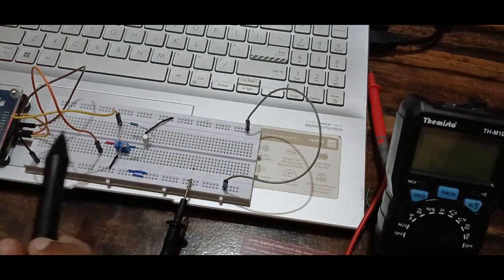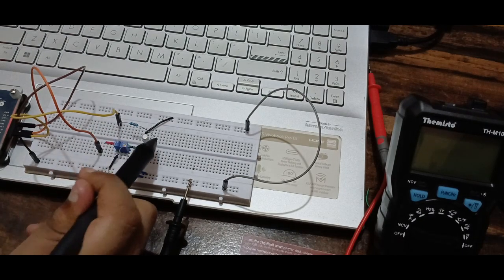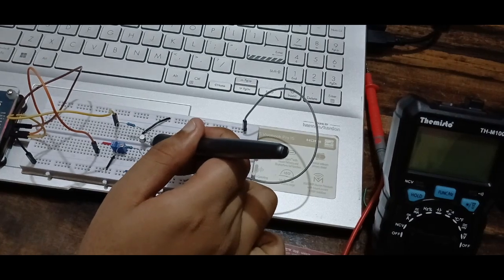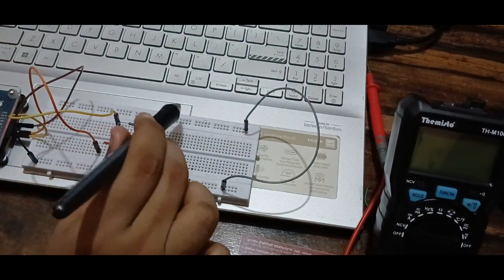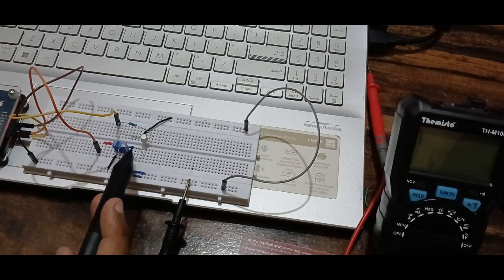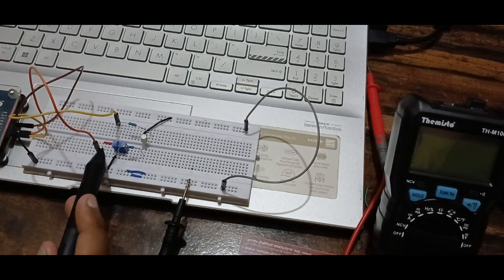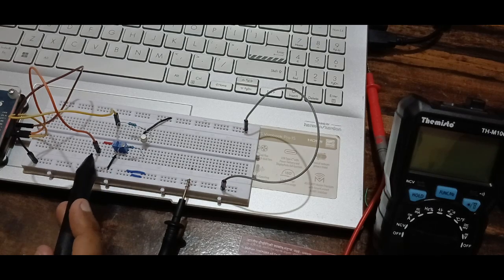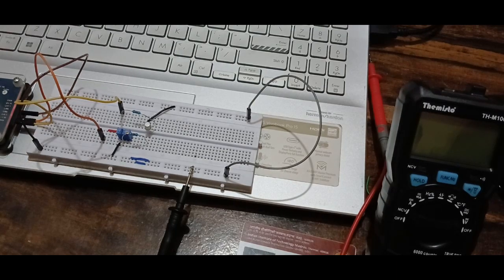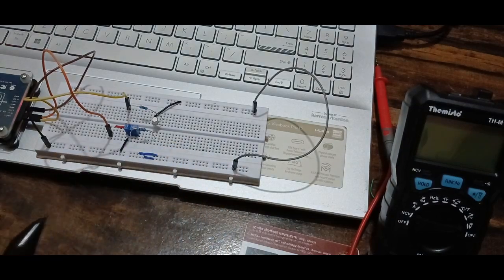I provide the VCC from channel A to the collector of this BJT, which is right there. This is our emitter, which is grounded. This is our base, to which I provided a resistor connected to the pot, and the third pin of this pot is grounded, and the first pin of this pot is connected to 2.5 volt. So now first I'll check the VBE, which is fixed at 0.7.